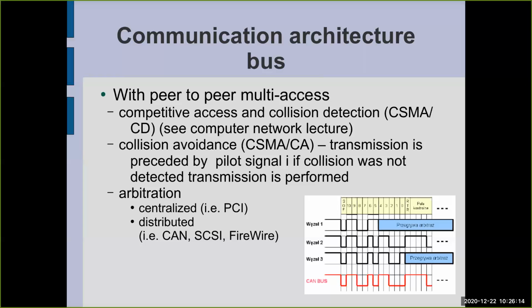So we are able to encode 0 and 1, but only high state or low state is dominant. So if we have 2 or more nodes and one of them sends high state, this state is dominant.